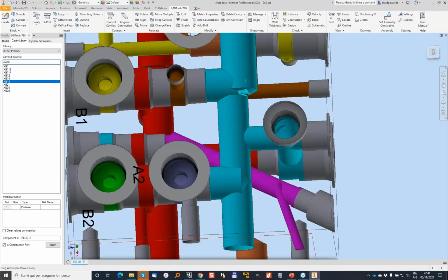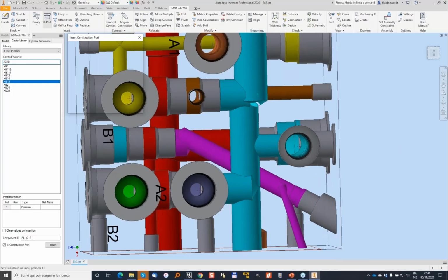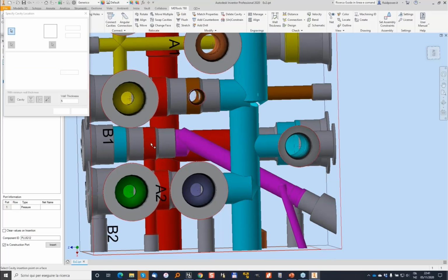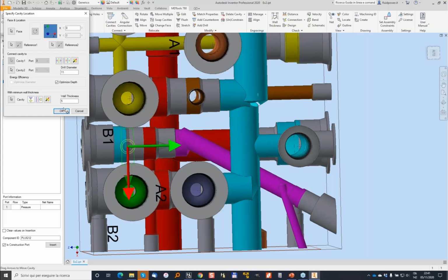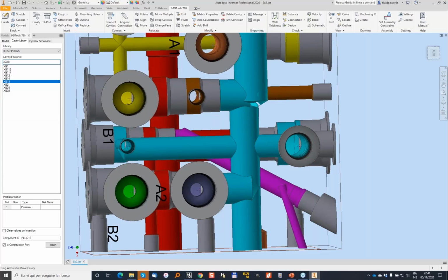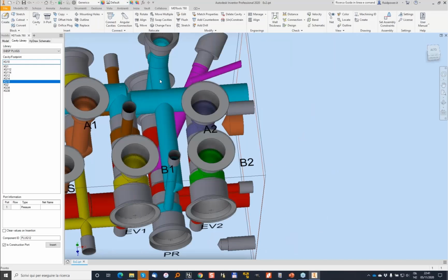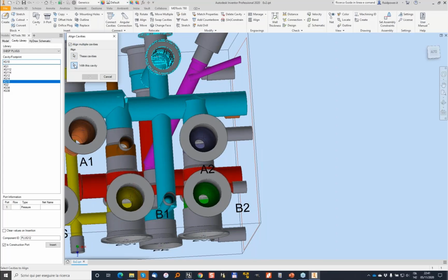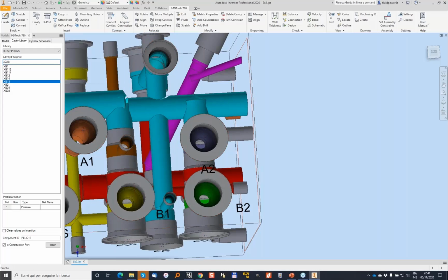And I want to make the connection, so export between port 3 and this one on the top face. Okay. This drill, maybe we can do an align, multiple cavities, 1 and 2 with this one to have a center-to-center connection.